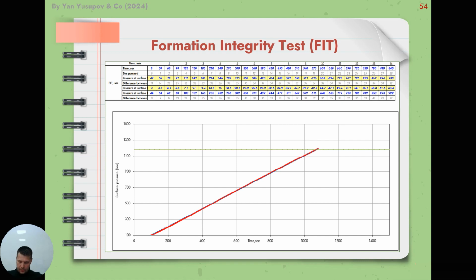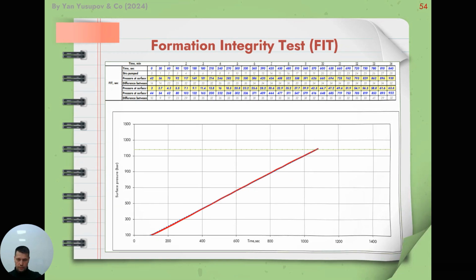Formation integrity test, FIT, is the method to test the strength of the formation and ensure it by increasing bottom hole pressure to design pressure. FIT is normally conducted to ensure that the formation below a casing shoe will not be broken while drilling the next section with higher BHP of circulated gas and fluids in a well-controlled situation. Normally, drilling engineers will design how much formation integrity test pressure is required for each hole section.